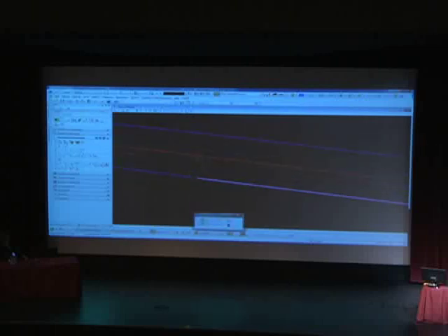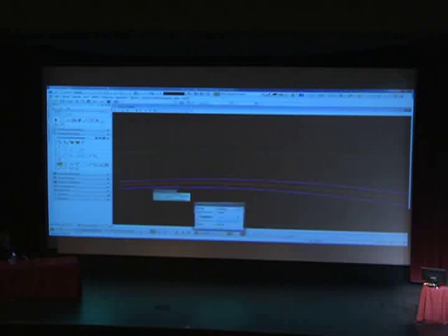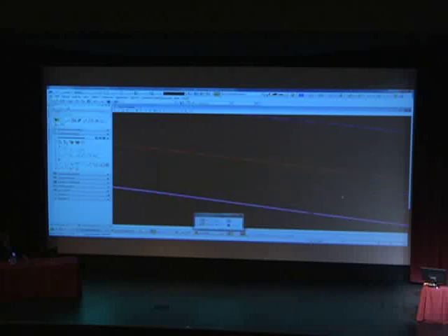Those yellow lines that you see there, those are the rules. So I could easily go to those yellow lines and change the 30-foot to a 24-foot if I wanted to. I just want to show you that that's what those yellow things are for. And then what I'm doing is I'm complexing that edge of pavement line into one single line now, so that it would be continuous. After I make that continuous, now this is just the horizontal geometry, right? I need to give it a Z value.